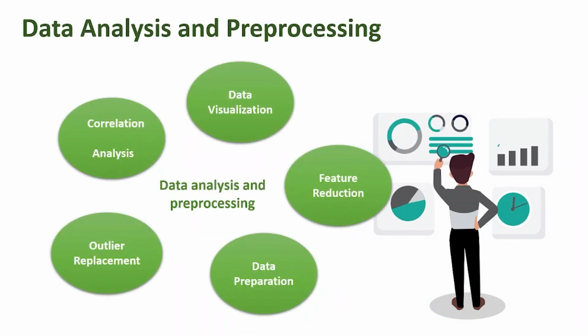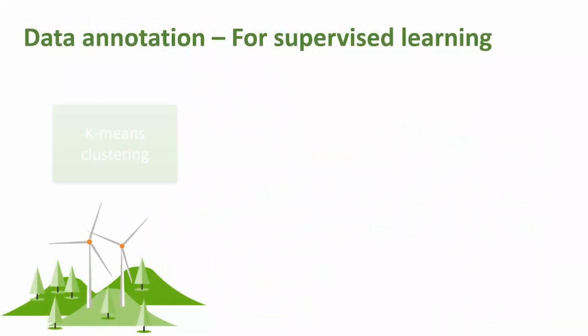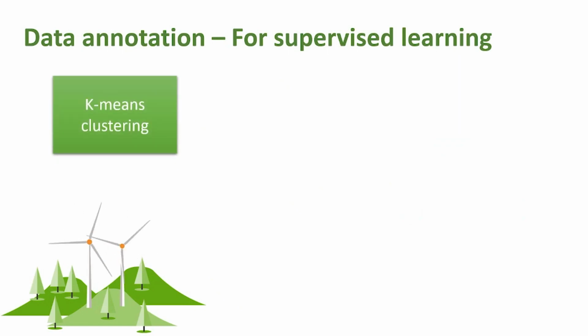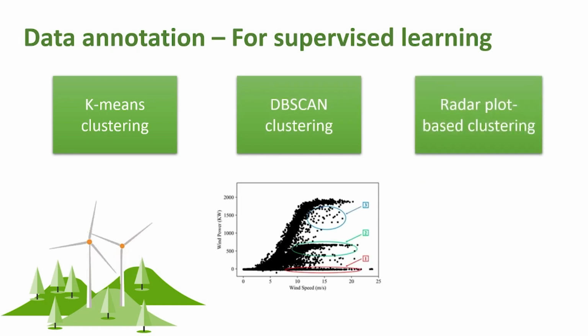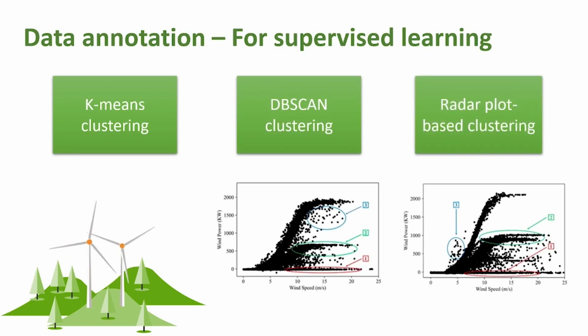Supervised learning models require a labeled dataset to annotate data as normal and anomaly. We used clustering techniques. Using these, we could identify and annotate power curve underperformance failures and gearbox failures. Since real-world datasets are unbalanced and not annotated, we proceeded with the normal behavior modeling approach.